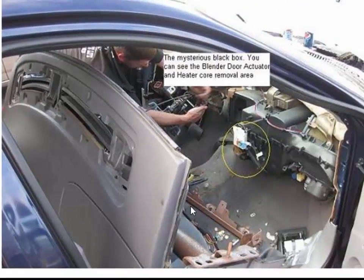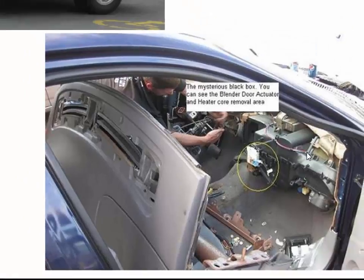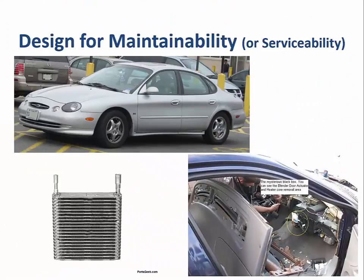And I found a picture actually illustrating that online. So that was about 6 hours of labor to remove and to put back. The total was over $1,000 of work, but only $150 was for the part. So that's a good illustration of poor design for maintainability or serviceability. In this case, it is too difficult to access the part that needs to be serviced.